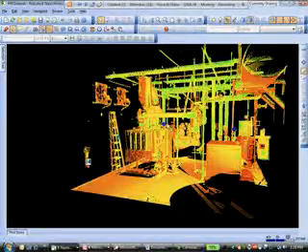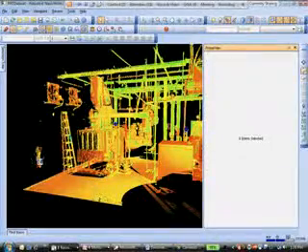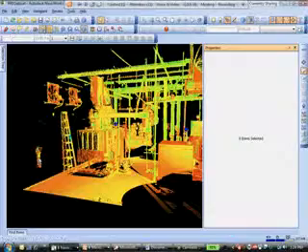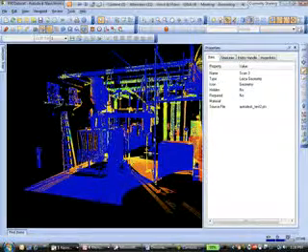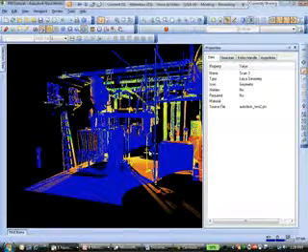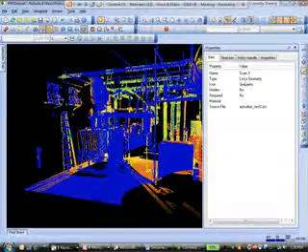Back inside of Navisworks, though, we can also utilize this external linking and link out to a more robust database. So if I open the Properties tab and simply click on one of these elements in here, it gives me some general information about the model. Now, in this case, with the point cloud, there's not a lot of intelligent information that's embedded in that. It gives us some basic information, such as where the source file was, what kind of application created it, and so forth.